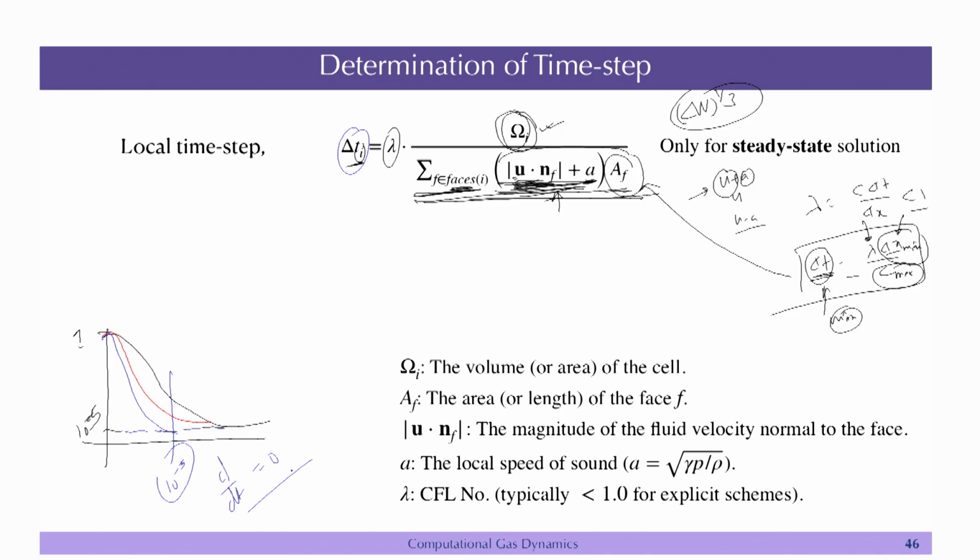So, you have these Navier-Stokes or Euler equations, where you can write du by dt equal to everything in terms of d by dx plus d by dy, let us say df by dx plus dg by dy, and so on, with a minus sign. If the problem is steady state, this thing will go to 0, but we will not do it immediately, because we do not know the solution.